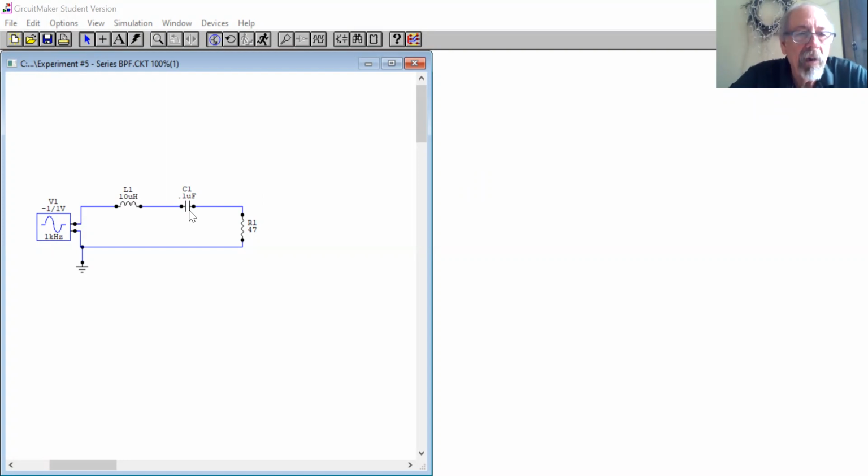The capacitors we already talked about in a prior experiment, at low frequencies, this thing will have an infinite resistance or reactance to the AC signal. The inductor at low frequencies will have low or zero reactance to the AC signal. And then they flip. That is, we go to real high frequencies, the capacitor acts like a short, the inductor starts to act like an open.